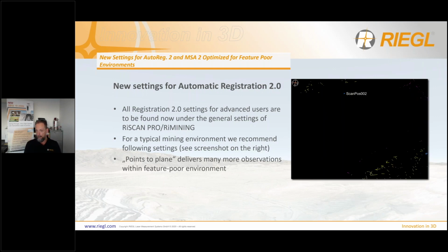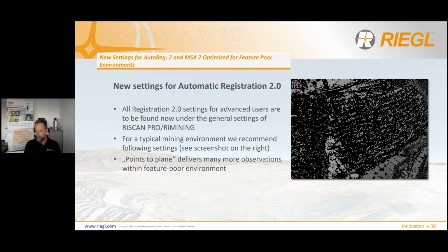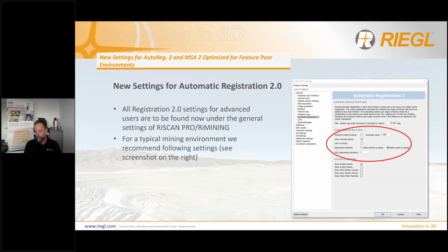And therefore, let me just go back to the settings. These were the standard settings with match planes to planes. And now we are introducing a new algorithm which is matching points to planes. The original scan data is matched to the planes. And you should only use this option in feature-poor areas like we have in mining.